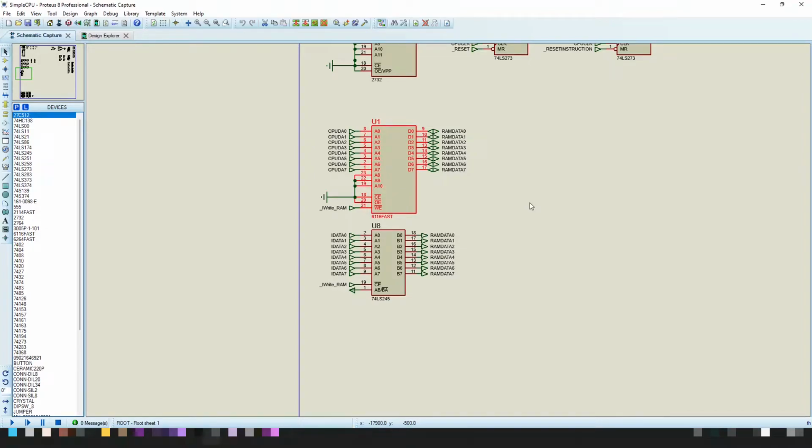And basically the states for the CPU, when it's doing a memory write, will hold the address value at its correct value first, and then in the middle of the state it will assert the correct logic level low on the RAM write, and then it will release that and set it back to high again before even considering to change the address here.